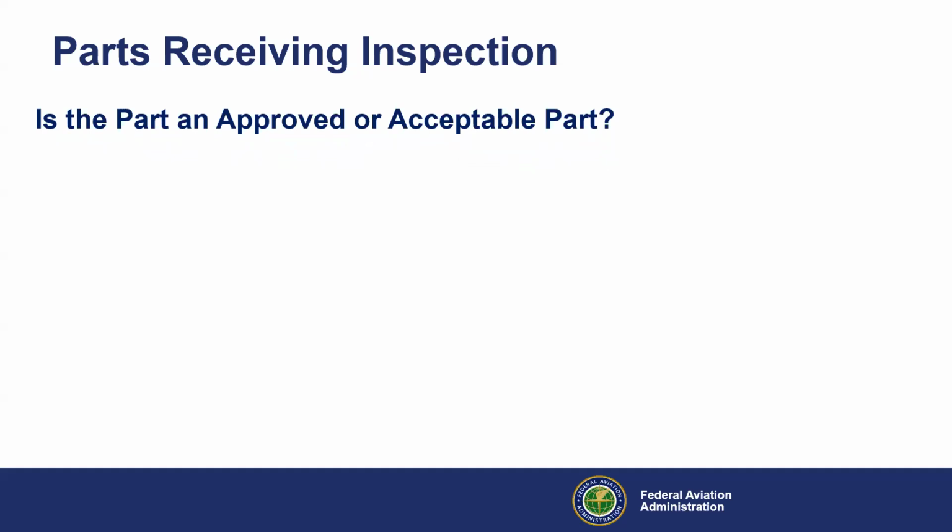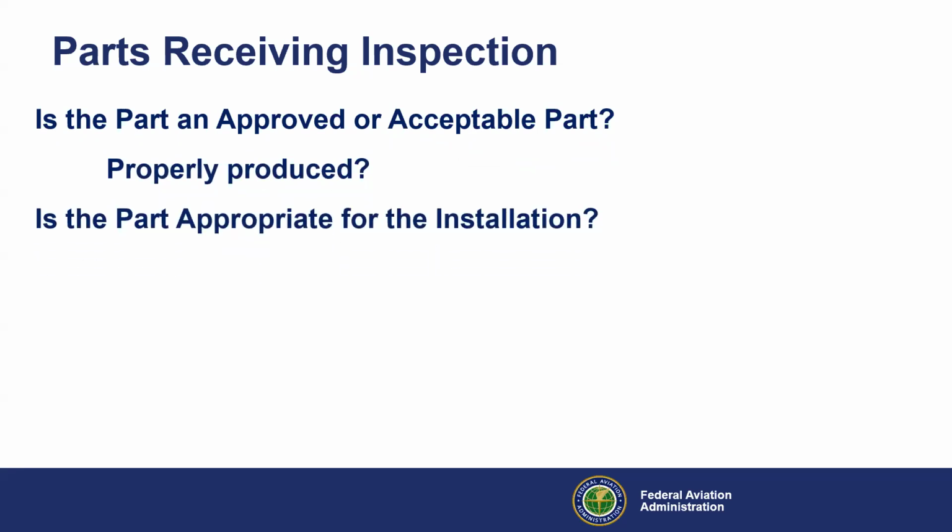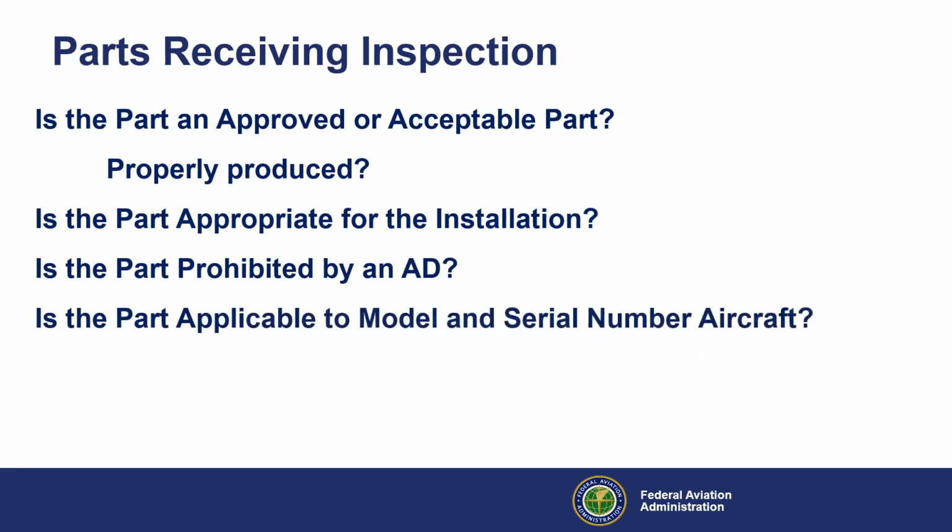Obviously, I ordered it, so I know what I'm ordering. But is it an approved or acceptable part? Was it properly produced? Is it appropriate for the installation? Is the part prohibited by an airworthiness directive? Is the part applicable to the model and serial number aircraft?